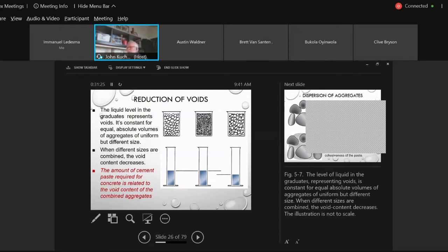If your aggregates are dirty and you haven't washed them, as you know from the wash sieve analysis, you can have deleterious material adhering to the aggregates so that when the cement paste tries to bond to it, it's a weak point. When you test concrete and you break that cylinder open, let's say, and you see that all those aggregates are split, have been sheared, you got a good concrete. That's what you want. You do not want pop-outs. In other words, when you test concrete, you don't want the failure around the aggregate. You want the failure through the aggregate.